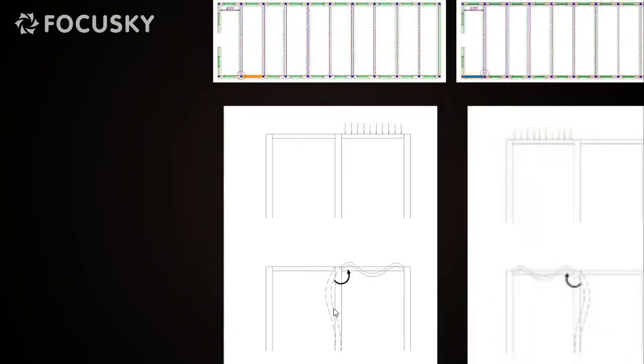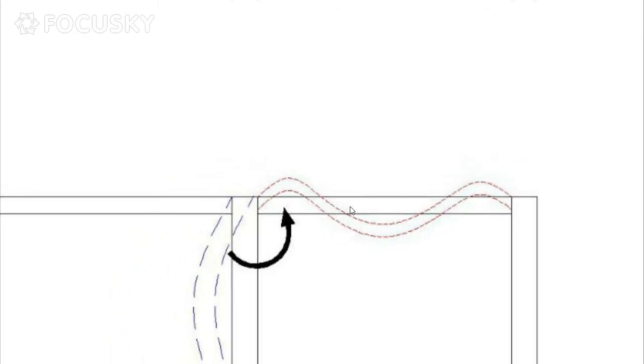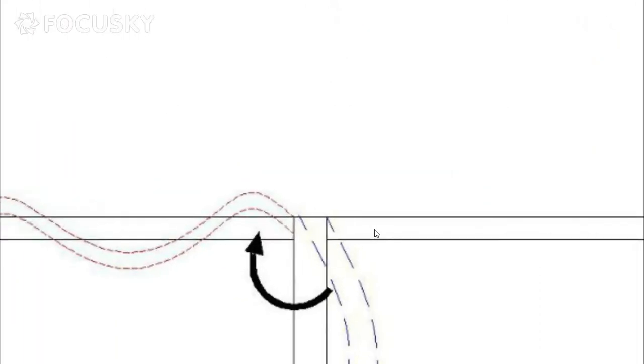So when the beam is loaded like this, the beam bends in this fashion because the beam is rigidly connected with the column. It is having a hogging moment at the support and a sagging moment at the midspan. This hogging moment at the support tends to rotate the joint and in turn tends to rotate or bend the column like this. Just assume that we are removing the load from the right hand side beam and we are applying the same load on the left hand side beam. So what happens? The beam is loaded like this, and it induces a moment like this and in turn rotates the joint and the column.